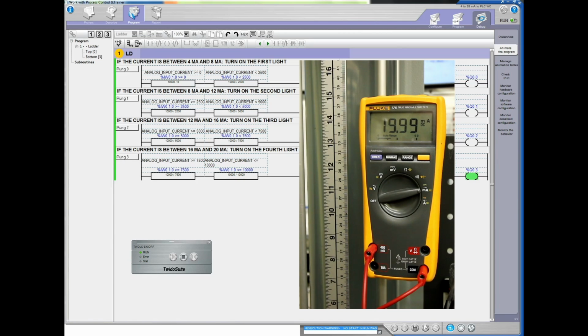So what I'm going to do is, because it's hard to videotape the screen, get the pump going and get the meter all at the same time, I tried to match it up, but I didn't get it perfectly. So what we'll do now is we'll drop the level, and in dropping the level, all I have to do is just open up my drain valve. So I'm going to open that up now, and we'll see that the value is dropping, and you can see that on our PLC program as well.